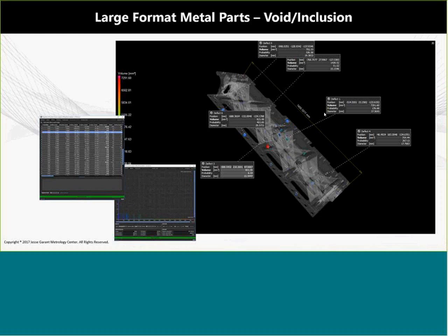So basically, for voids in solder, or lack of solder in BGAs, CT is a fantastic tool because you can classify and see how much void there is. Because, as you know, when you're looking at a radiograph, I'm assuming you're probably doing it in an oblique. Yes. That's great, but it doesn't give you a true sense of depth. And that's where CT is fantastic, because it'll give you that depth. It'll tell you exactly where it is, and it's somewhat automated, whereas traditionally with regular X-ray, there's no indexing. Okay.